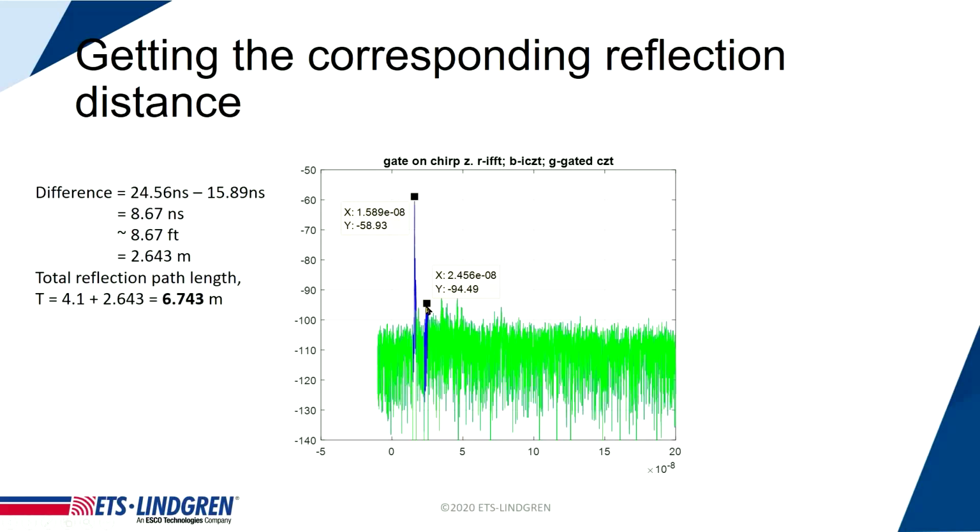The reason is that large reflections in the time domain may not necessarily correspond to a large contribution at that frequency: in time domain, the signal is a convolved signal with all the frequency information in it. So we don't really know at which frequencies a large reflection might be occurring. That's why we have to use trial and error to find out which reflection is dominating at that frequency.